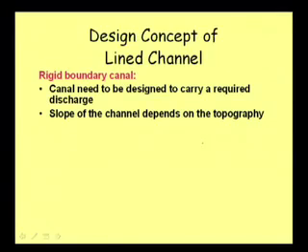Say, for example, if I draw this, this is the canal and the natural topography is supposed to be like this. We may not design a canal following it up and down, but we can design a canal by filling up some portion here, then cutting some portion here and then filling up. We can design a channel of uniform slope. Okay. So marginally we can change the existing natural slope and have our desired slope to some extent, but it is not that we can change the slope grossly.